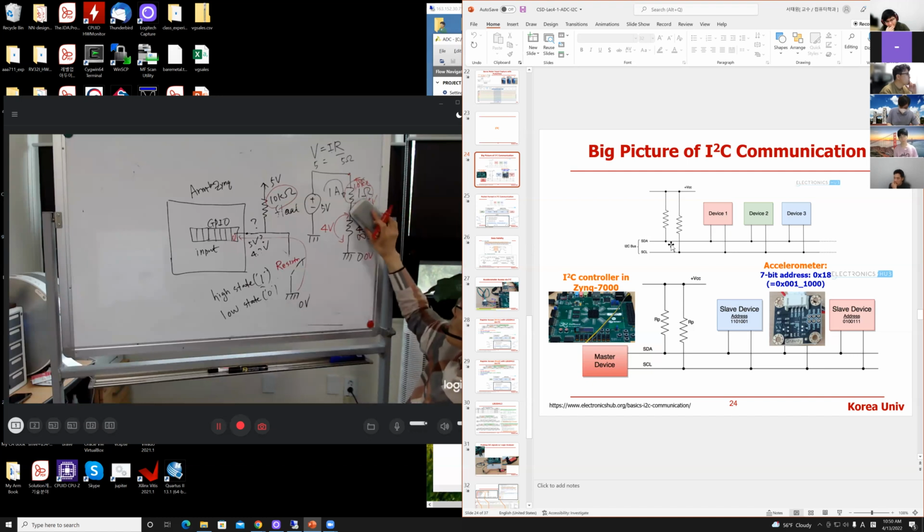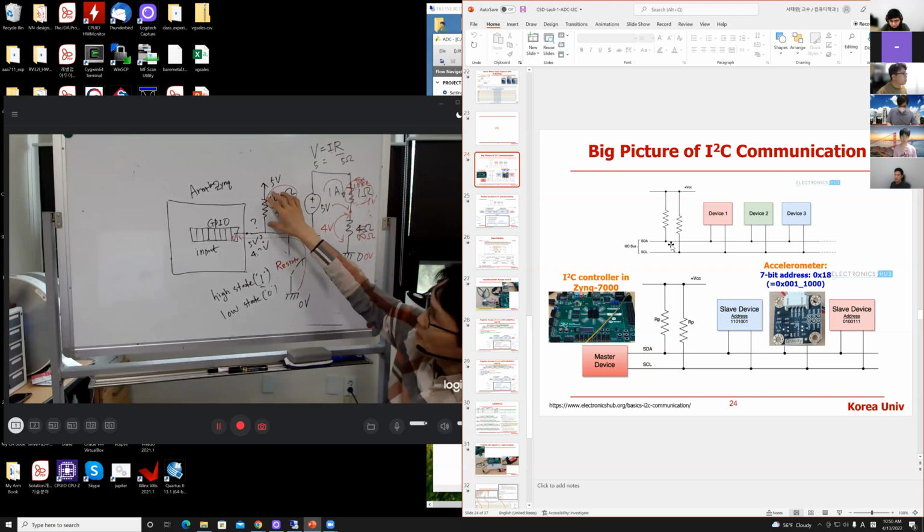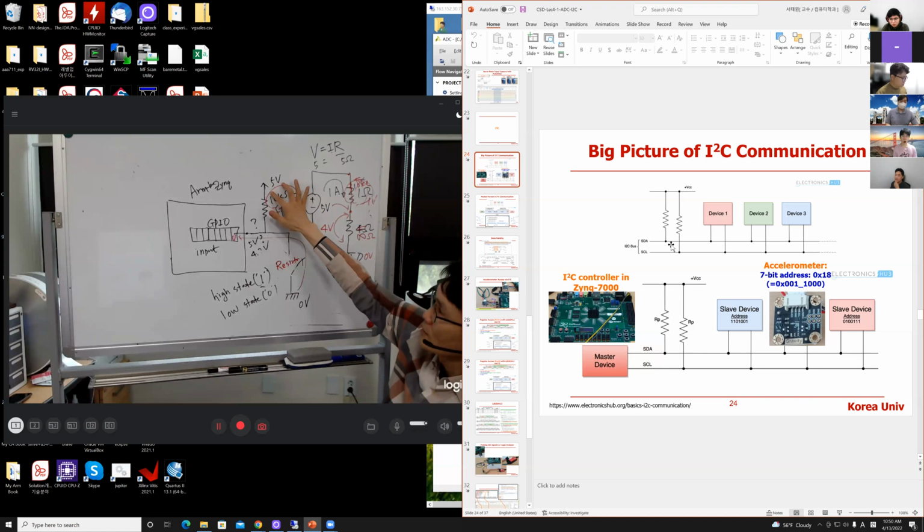So the voltage of this node is very close to 5 volt. You can just ignore this connection, no resistor. That is an intuitive way to interpret this electric circuit: think about the extreme case. You have infinity, then a very small resistor, so just ignore it. The whole 5 volt is applied to that resistor.